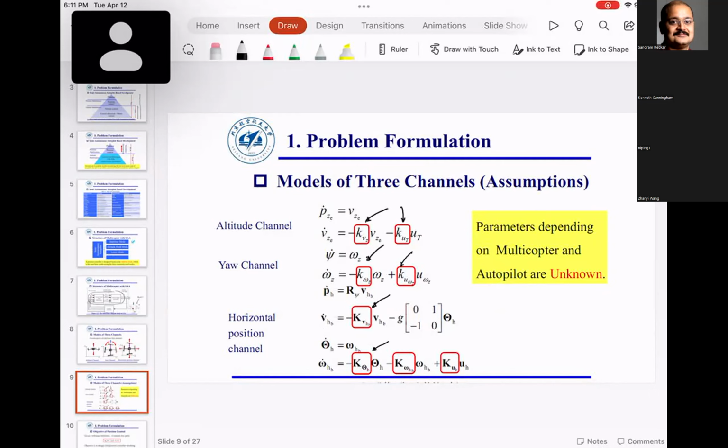But for the stabilization, the inner PID loops need to run at a very, very high speed, and the actuators should be able to respond to those high speeds. Because what may happen is, even though your control loop is running very fast, if your actuator, for example motor speed, is not able to change very quickly, your controller will not work. So what you want to do is match these two.